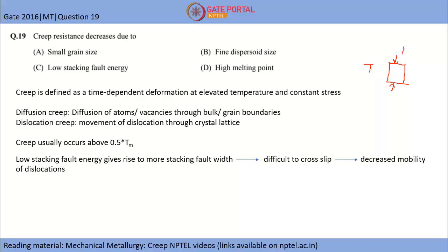So let's say P is the load applied, which is generating compressive stress throughout this cylinder, and we are holding it at time T. So what will happen if you are below the yield stress also, this material after a long time will try to deform or relieve the stresses caused by this load. Hence, this deformation caused by a constant stress at a higher temperature is basically creep.